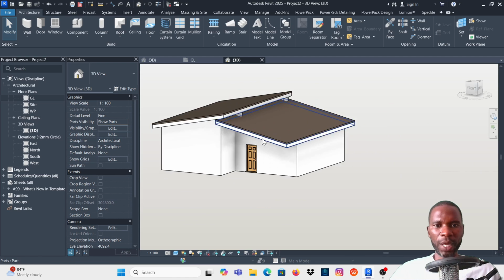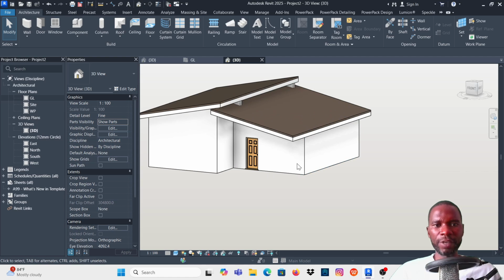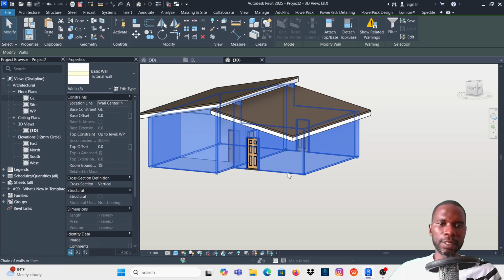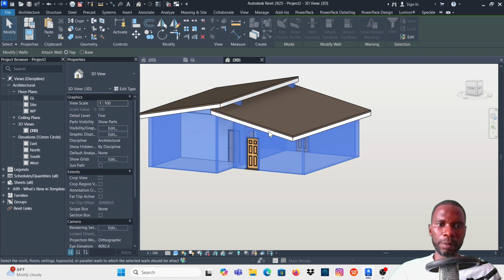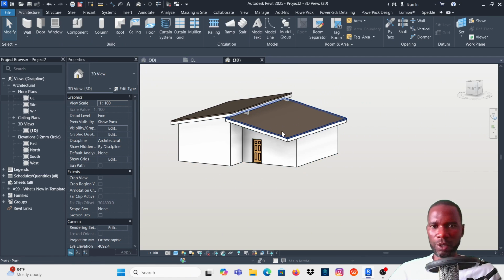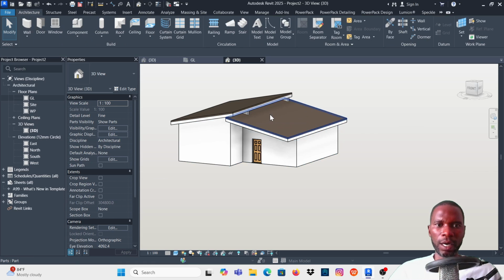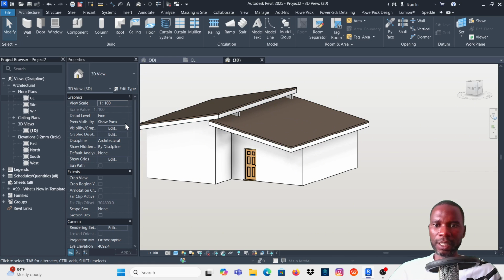All right, now I also need to attach these walls. I don't want that attachment there, as you can see from here. So I'll need first to start by attaching these walls to this one. So I'll hover the cursor there, tab, then hover the cursor there, tab, select, then attach. Let me pick this one. I can't even attach because it's already attached there for some reason. So I'll select this one, tab, select on it, then I'll click on detach. Let me detach. Oh, the reason why I can't select, as you are working, make sure that you are on original.